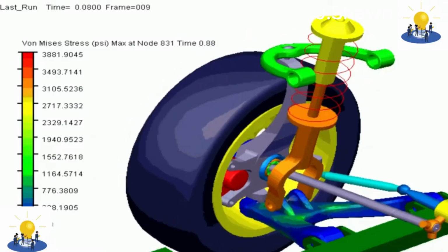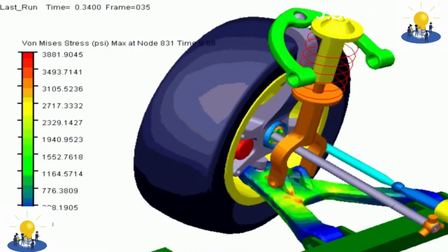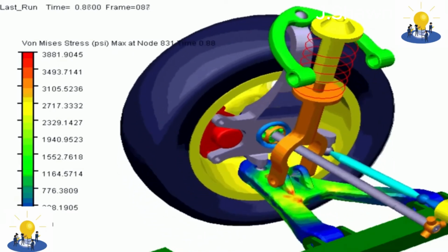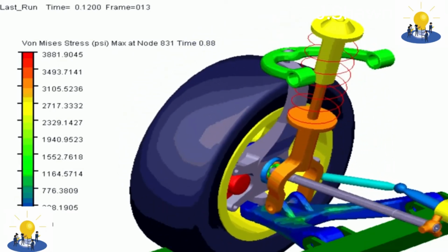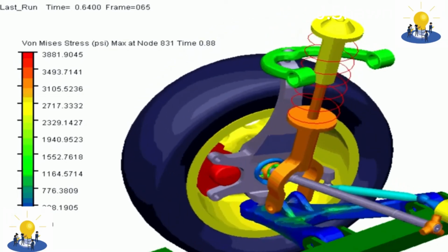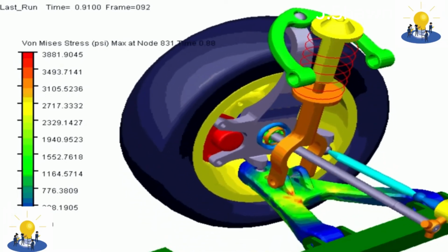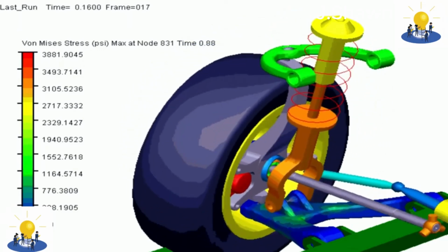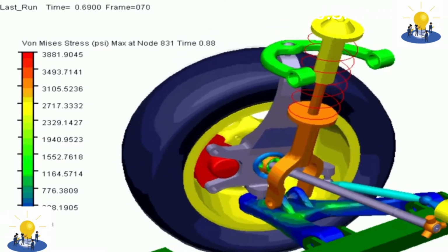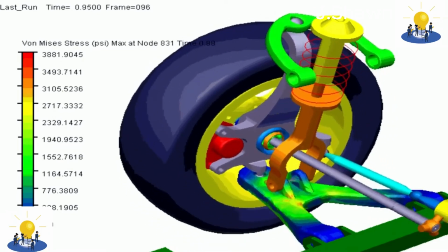They also provide increasing negative camber gain all the way to full jounce travel, unlike the McPherson strut, which provides negative camber gain only at the beginning of jounce travel, and then reverses into positive camber gain at high jounce amounts. Disadvantages. Double wishbone suspensions are more complex, impose more difficult packaging constraints, and are thus often more expensive than other systems like a McPherson strut.